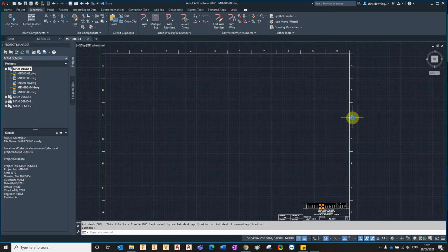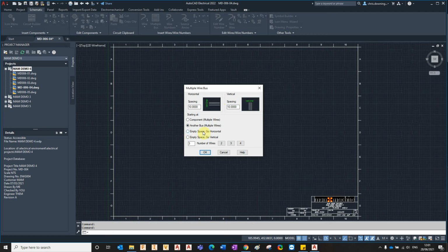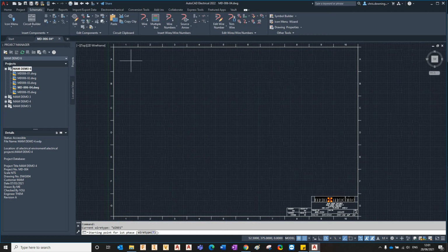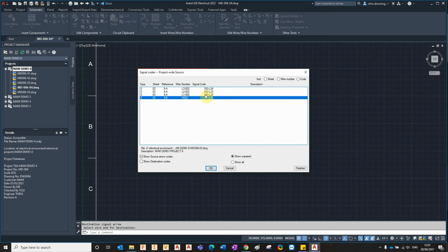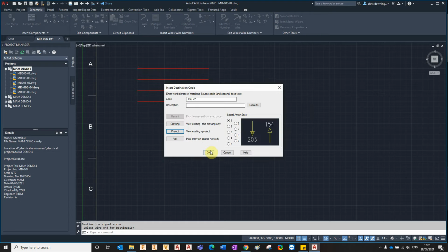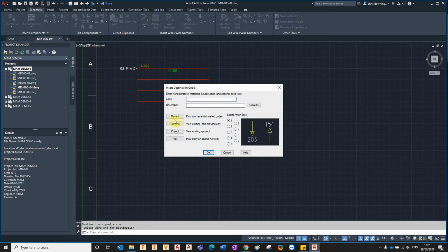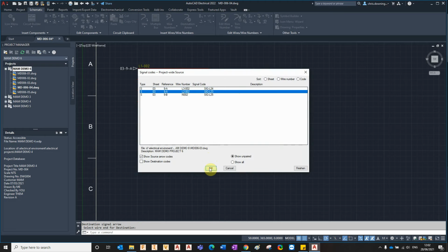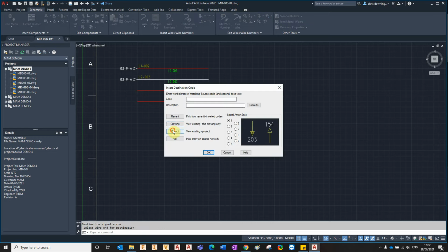This is where I'm going to start doing the control circuit, and I'm going to start bringing across maybe just a multiple bus from an empty space with 4 poles, somewhere like that. And I'll bring on my destination arrows, and what you'll notice this time as well is that we're able to bring the wires across, but it also updates the wire layers as well with the right colors. So bring those across, numbers the wires, updates the wire layers, and cross-references the source and destination arrows.